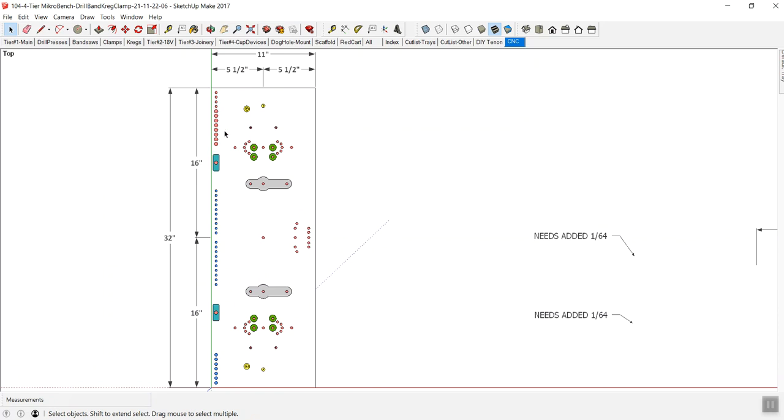My color coding, I've hopefully covered that somewhere else, where typically this off red means go full through. So you can see those here, here, and here. And then the blue means go down about 0.9 because I want to put some pencils or bits in there. I want to be able to put stuff in there, but I don't want them to go all the way through. The gray is kind of a reminder that that's tabs. The green is a reminder that that's a little bit greater than a quarter inch, so that's probably going to be 0.375. And then this blue here is going to be 0.375 for sure. And then the yellow means it's actually off of the chart, so it's not going to pick that up.